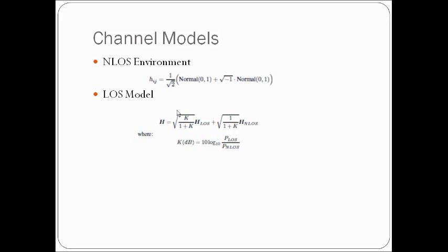These channels can also be modeled analytically, in which case all channels between transmit and receive antennas are considered as SISO channels and also considered to be independent and identically distributed. It is a fact that these channels could have spatial correlation between the links, and a channel with a particular correlation matrix can be formed.